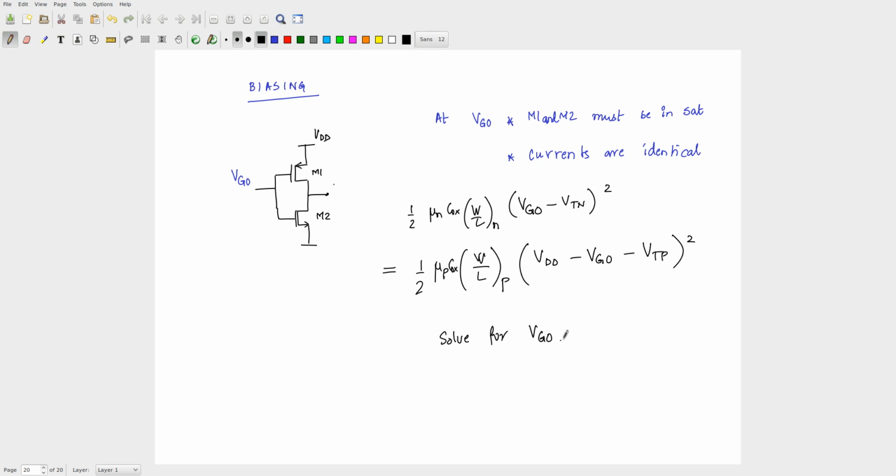Okay. So, we will see how exactly, finally you want a bias circuit that has some feedback so that it is stable and all of that. I am not going into that in this course. We will take that up when we are doing the laboratory course next semester. The aim of what we have done over the last 2 lectures is to just motivate the fact that if you want very high gain, you cannot live with a simple resistor. You need to have an active load, because the active load allows you to get high gain with the same value of VDD.